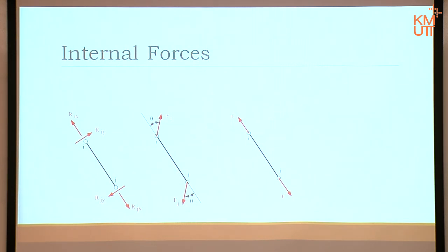Since Fi and Fj are equal, I will just call them F. However, now we should notice that we are talking about internal force. We cannot see internal force unless you start cutting it. So let's cut at any place. Let's call it any place at x from I. It could be x from J, doesn't matter. It's going to prove out the same.